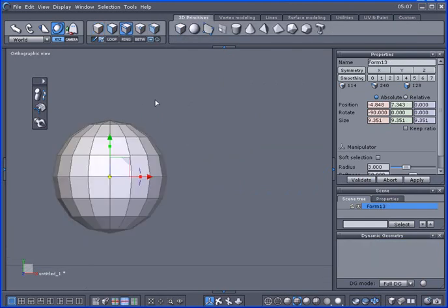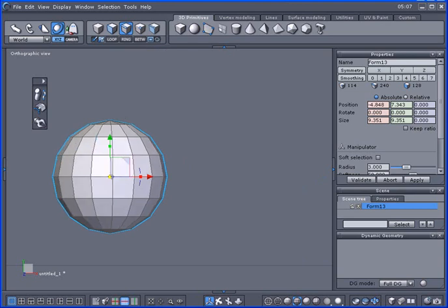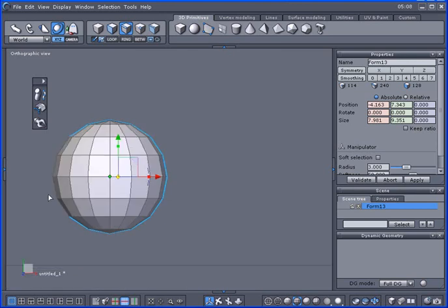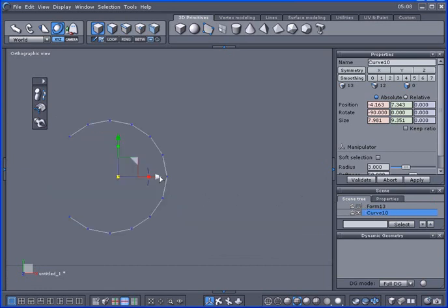Here's a way that you can bend one object around another object using the bend tool. What I'm going to do is select the edge over here, as I'm looking at it in front view, and we'll just go ahead and loop this here. And I'm just going to shift click to select a few of these. Go back into front view. I'm going to use the curve extraction. We'll just hide that, and there's our curve.